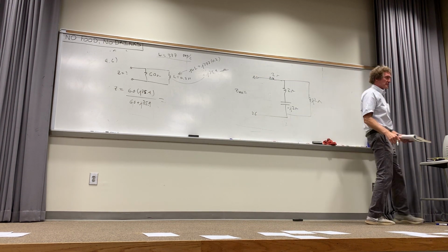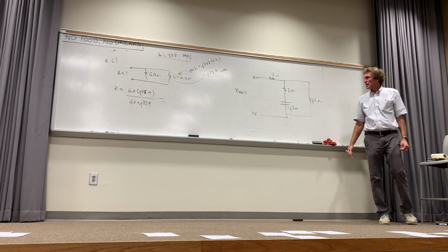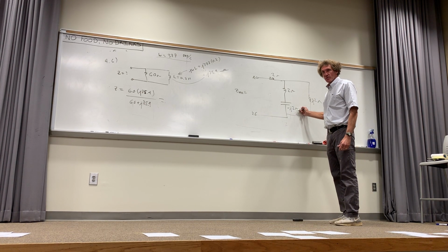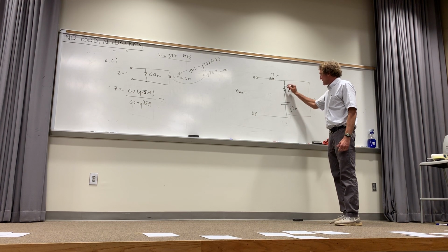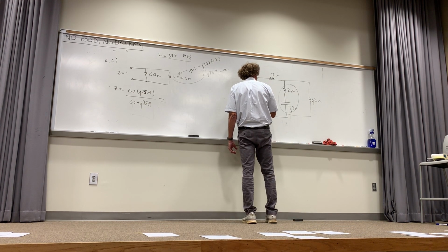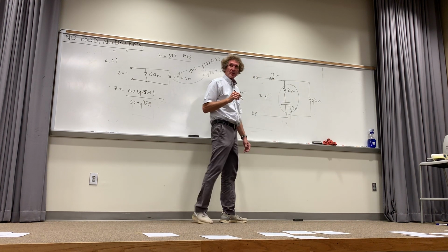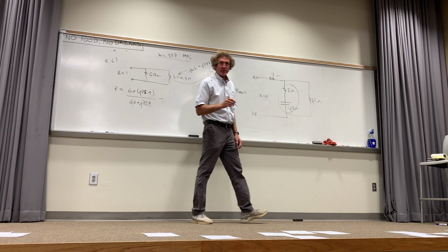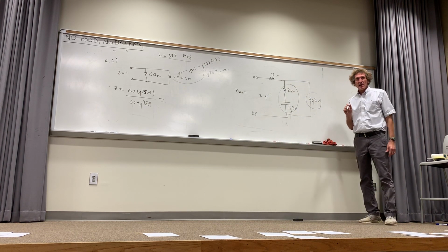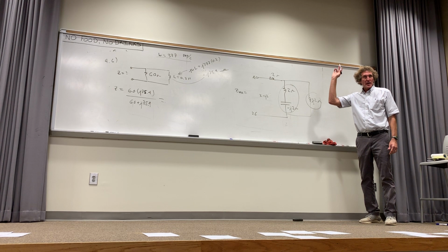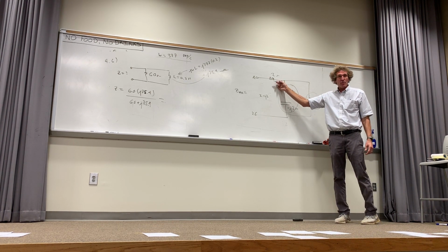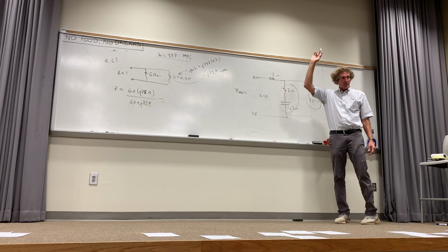Now just take a look at this, because you're going to get this. You all see these two are in series. You agree with me? So the impedance of this leg right here is just 2 minus J2. Are you with me? Now, y'all see that this J2 here is in parallel with those two. How many see that? And you see that the parallel combination of these two plus 2 would be the total impedance. Do you agree? How many agree with me there?